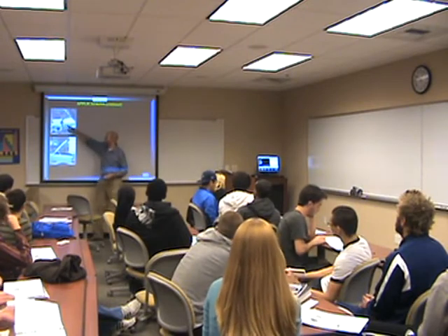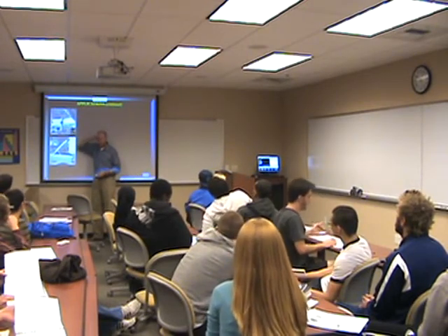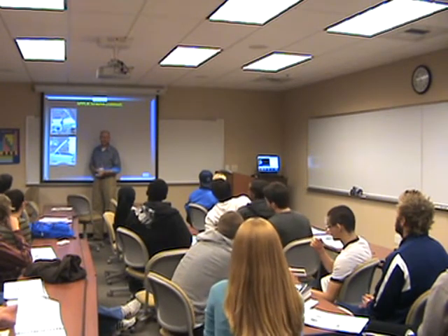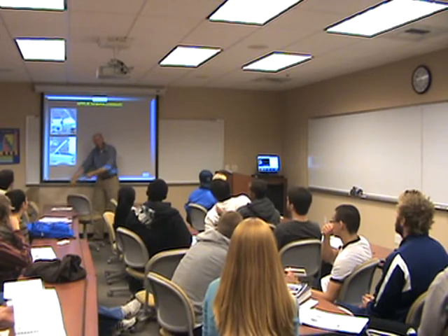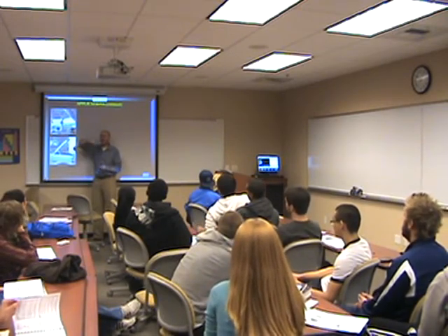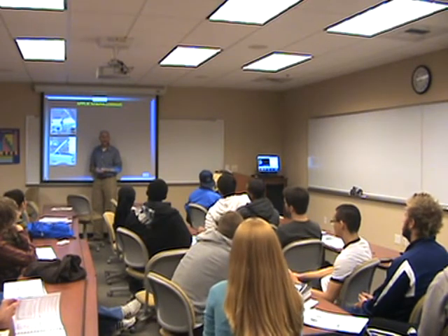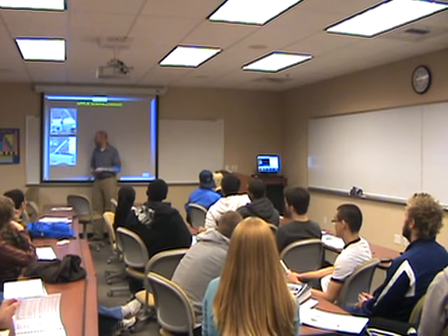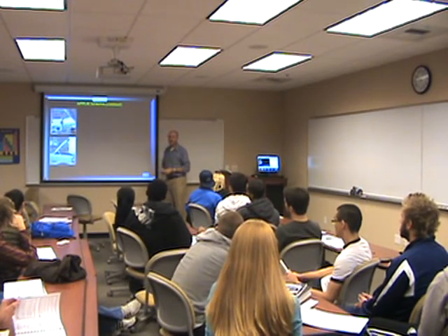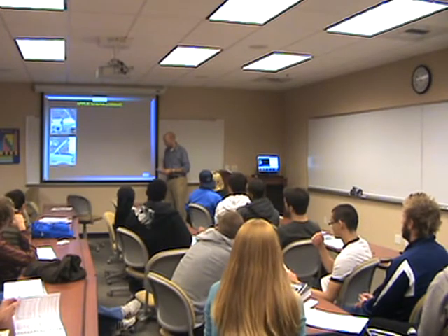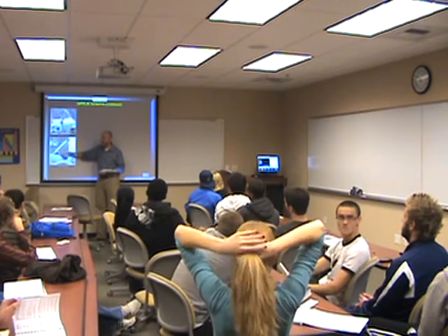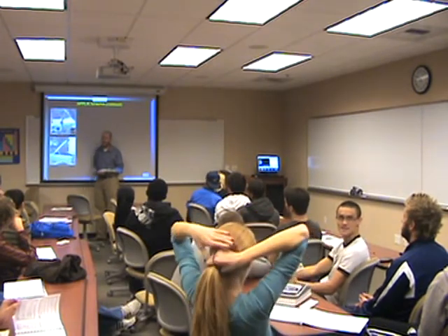Similar concept here. Here we have a torsional spring. Do you know what a torsional spring is? Have you ever seen a clothespin? It has a spiral thingy on it, and as you twist it, the spiral wants it to close back in. So that's a torsional spring. What's the purpose of this torsional spring on this car? To hold the hood up. Right, so as this lifts up, you get potential energy in that, so you want to lose the potential energy in your spring. That's how you would go about designing it.